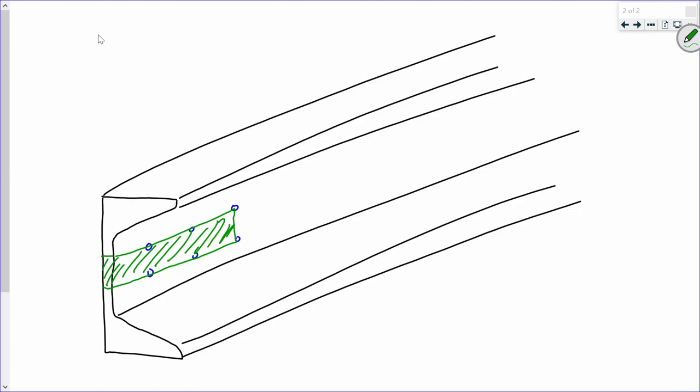Yes. So if you've got a grid-like pattern of bolts, like a rectangular grid, you're only going to have one net area, and then however many holes go through that section. If you've got a staggered connection, you're probably going to have more than one failure path. So literally through each failure path, just count up the number of holes that you're cutting through, and if it's 3 holes, it's diameter of the holes times the thickness.